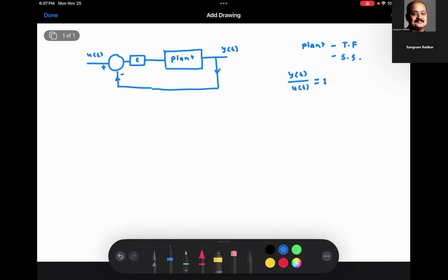Now, I did not talk about a lot more detail in the math, but if you want to study the mathematics of control systems, there is an entire course on linear systems taught in Triple E that will teach you all the basics of control systems. At the end of the day, the idea is this. If you have a plant, you can form something called as a transfer function. So transfer function is nothing but the Laplace transform of output divided by the Laplace transform of input.